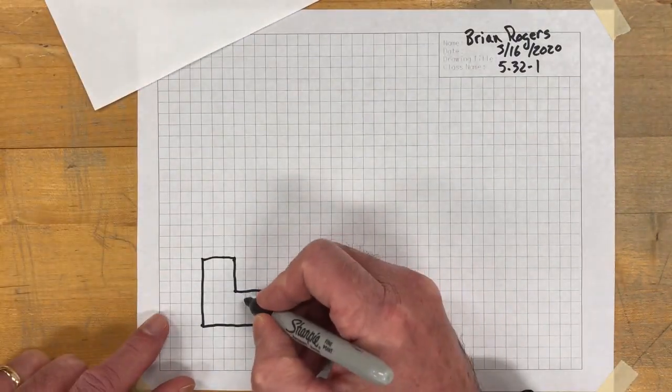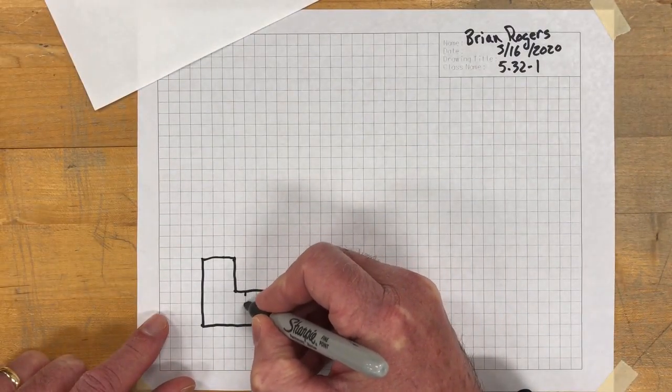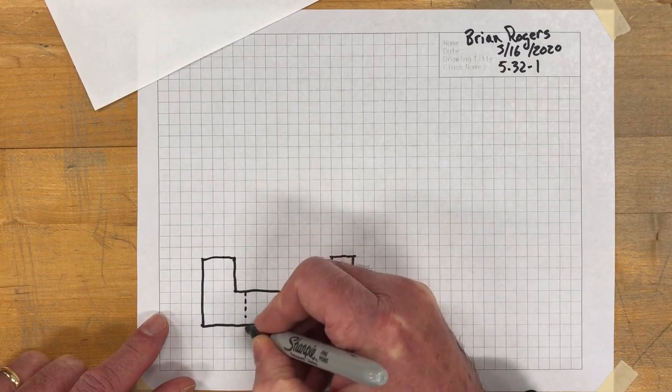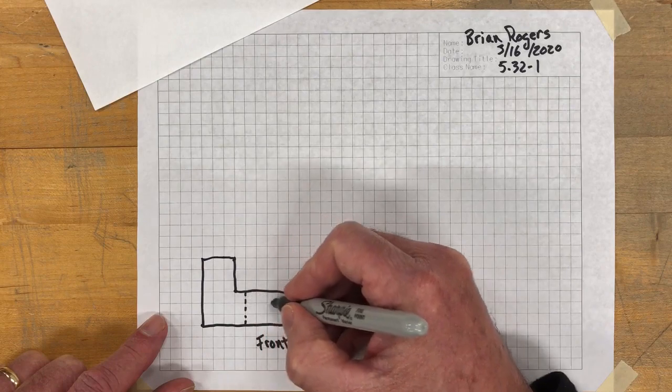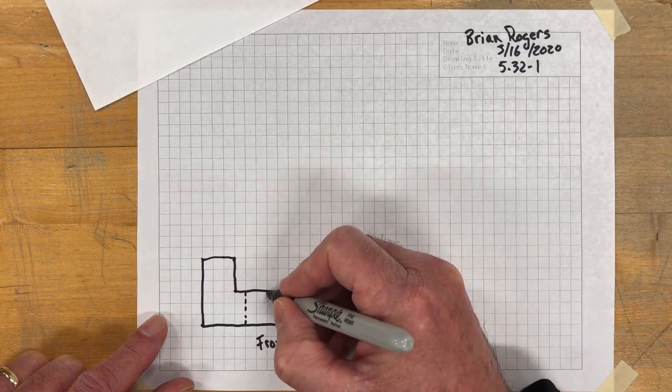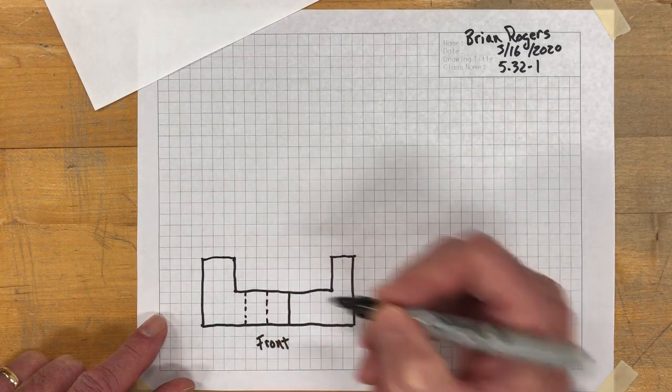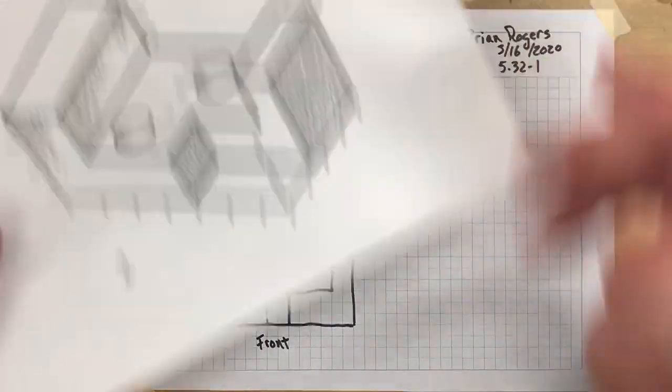So then here's how it works. 1/4 inch over, one block, I'm going to draw a hidden line here indicating the left edge of the circle. Now I know it's 1/2 inch in diameter, which means 2 blocks, so I'm going to go ahead and put a matching hidden line right here. All right, so that takes care of the leftmost hole.